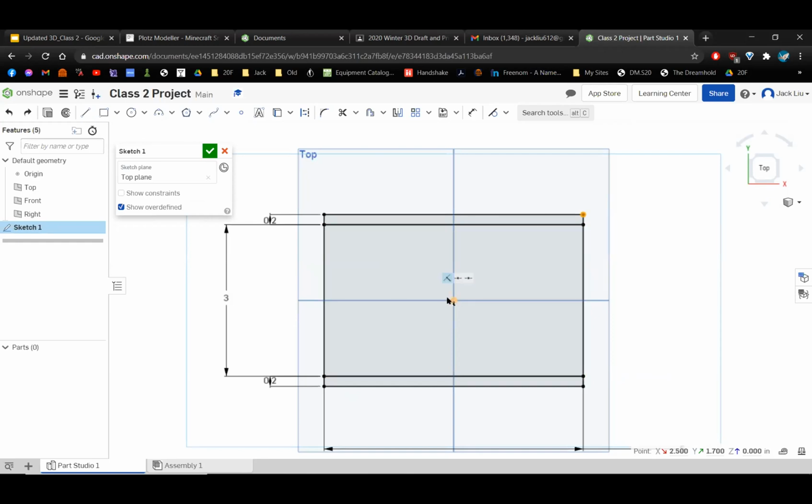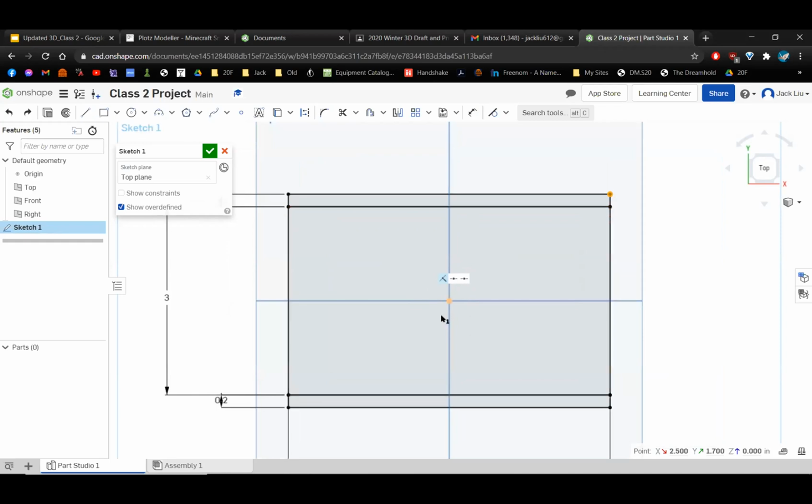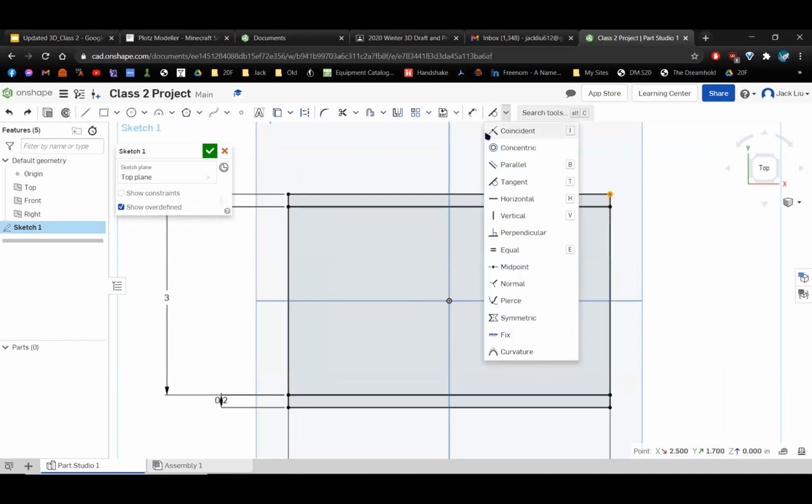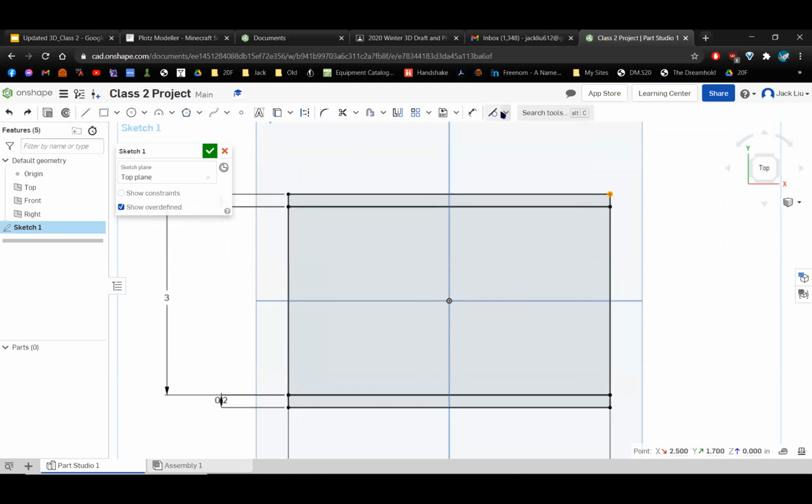To fix that, if you go to the center of your sketch, do you see 2 different points? Kind of. So if you click one of them and then use the coincident constraint and then click the other, it should make everything go away, or it should make everything black. Oh yeah, it's gone. Okay, thank you. Okay, awesome. Yeah, no problem.